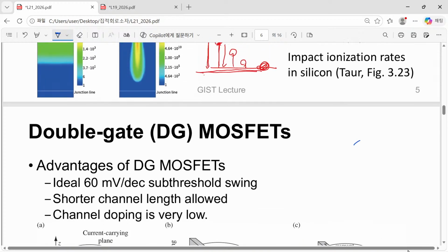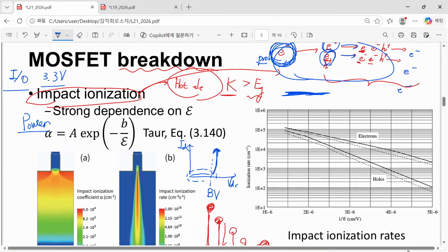Then we need extremely high breakdown voltage. Below this breakdown voltage, our transistor works as a normal transistor, and beyond that, it stops its normal working and just conducts a lot of current, and eventually it is mechanically damaged because it conducts so much current. This high current generates a lot of heat, and that actually demolishes the crystal structure of our silicon devices. So this is the breakdown.